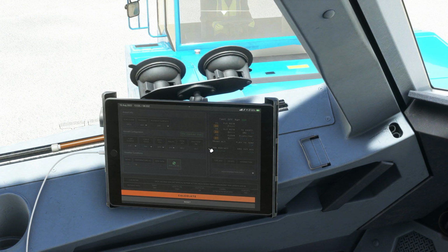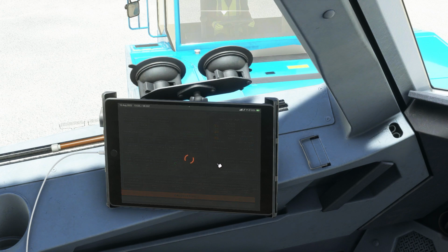As I'm tuned to ground, let me change the frequency so that we don't hear this radio communication. Okay. And the maximum takeoff weight, the center of gravity percentage is calculated 29.7. It was over there coming as 31.2. Anyhow, we can just ignore this. Just get the temperature, the wind, the QNH, and plus the temperature.